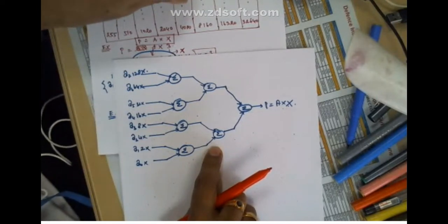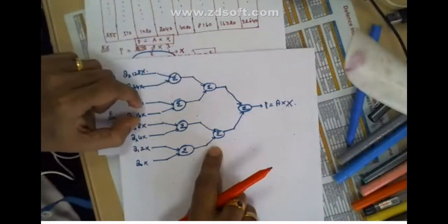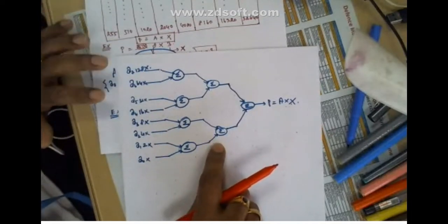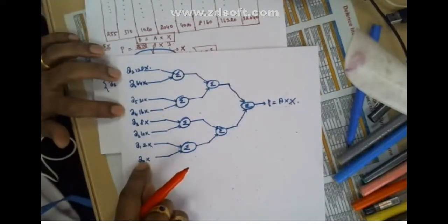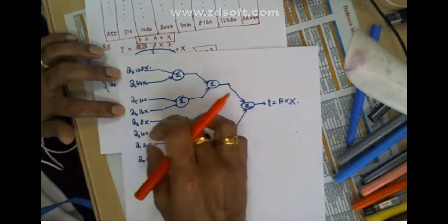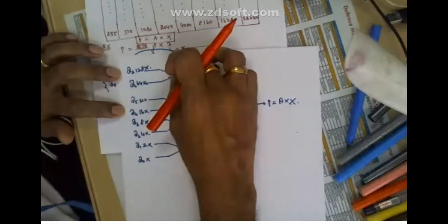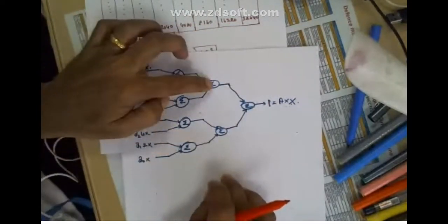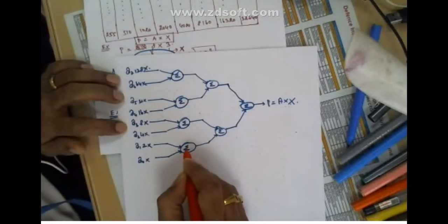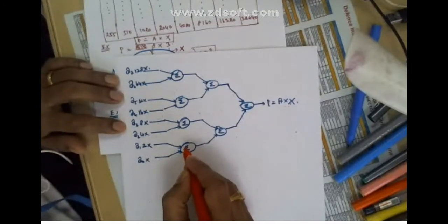The value that we are going to take from the table, that value and this value will be sent to this adder. These two values will be sent to this adder. So this adder is a generic adder, common adder. If A naught is 1, this value will be taken. If A naught is 0, this value will not be taken. So these two will be added here, these two integer numbers will be added here, then that result will go here, and in between the carry will be propagated inside, right? So that much delay we need to wait here now.